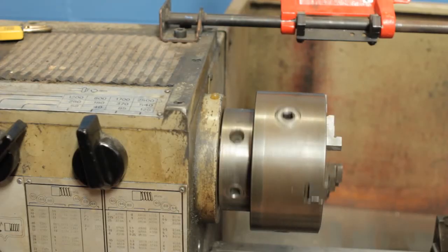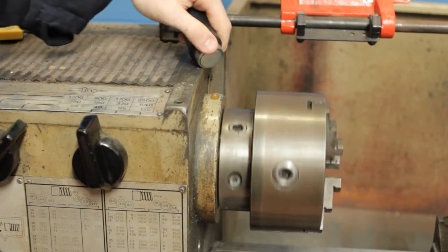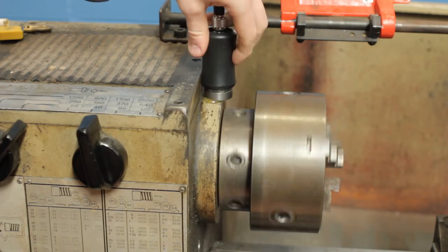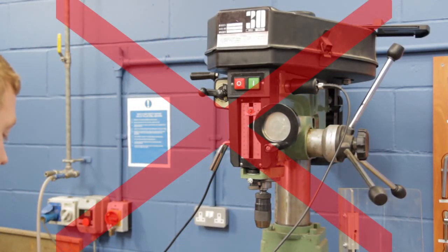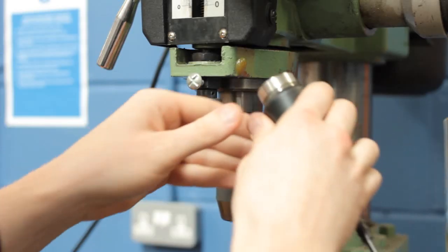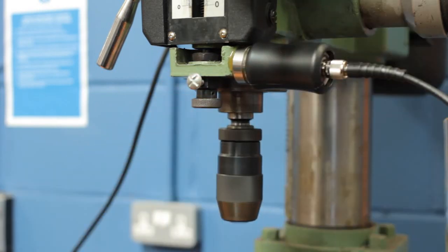It also means that we need to be fairly close to the bearing we are measuring. Orientation is not an issue, as sound waves travel in all planes. However, joints reduce the amount of sound transmitted through a structure. Ideally, select a point on the machine that is as close to the rotating element as possible, but with the fewest junctions within the sound path.